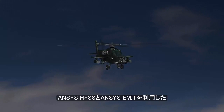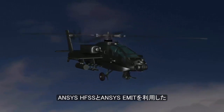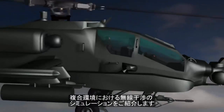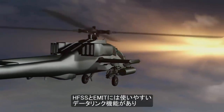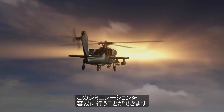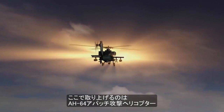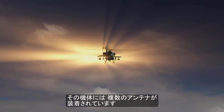In the next few minutes, you'll see how ANSYS HFSS and ANSYS EMIT work together to provide a complete solution for radio frequency interference simulation in a complex environment. The HFSS and EMIT data link, with its ease of use, facilitates this complete solution. As an example, we'll use an Apache AH-64 helicopter with a collection of different antennas mounted on the aircraft.